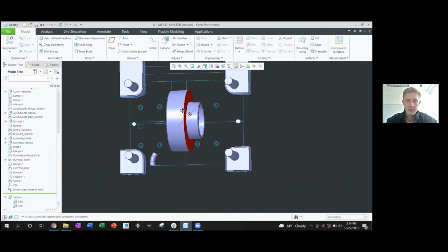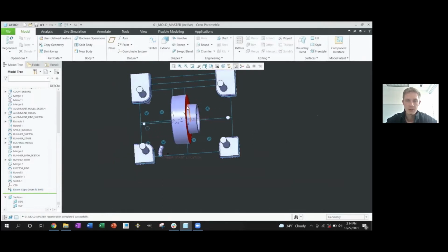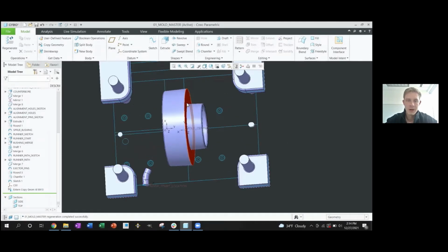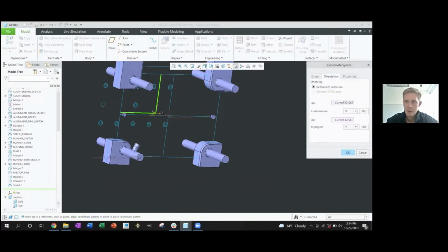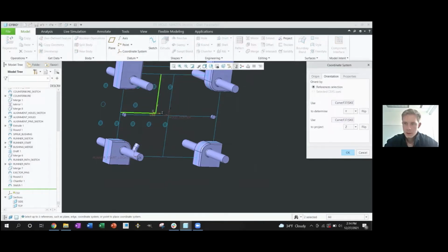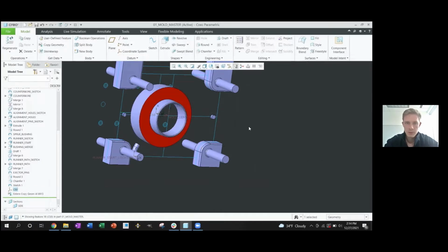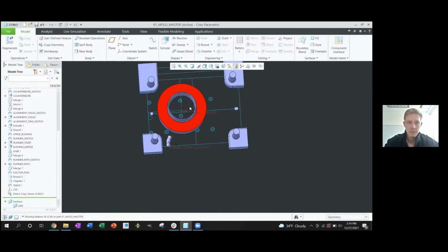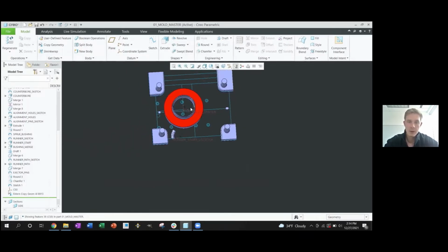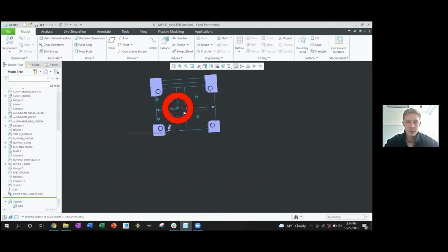Based on the parting lines that we talked about in the last module, this part is not going to be a good orientation. So we'll need to rotate this coordinate system here. It should be, if we flip our Y and Z, there we go. So now we have our part in position. It's still not quite where it needs to be, but at least it's got the orientation that we're looking for.